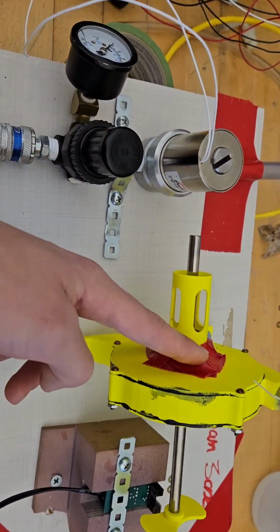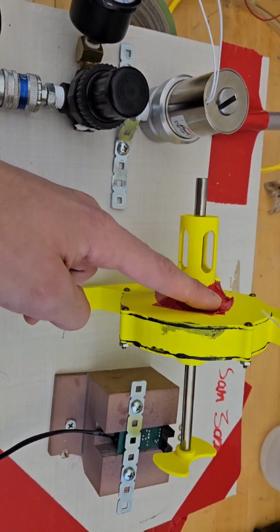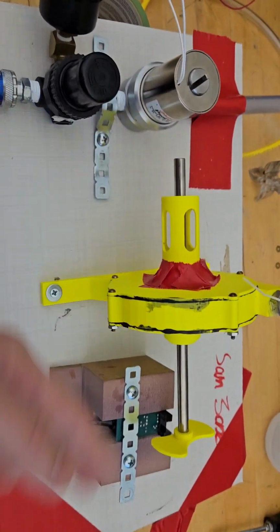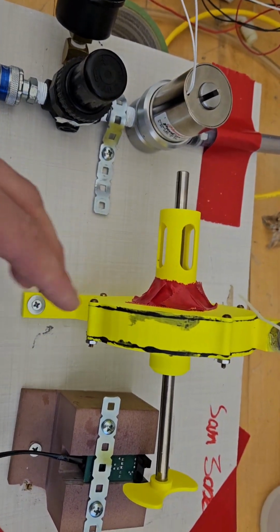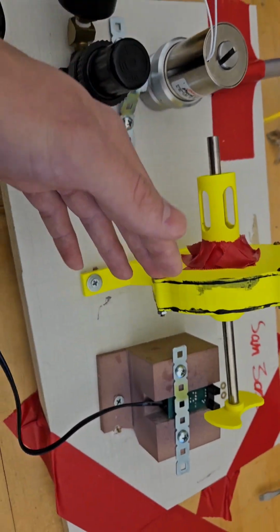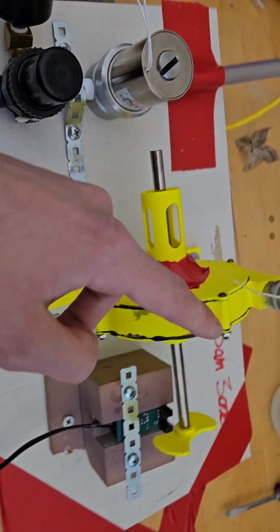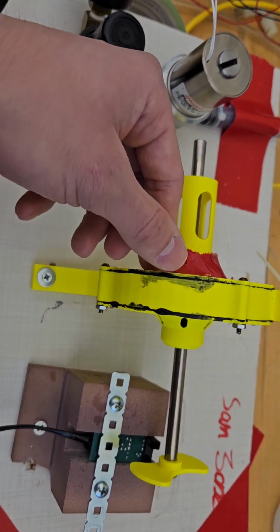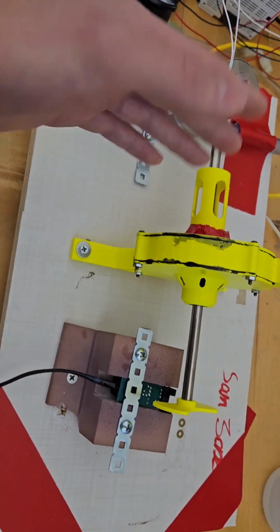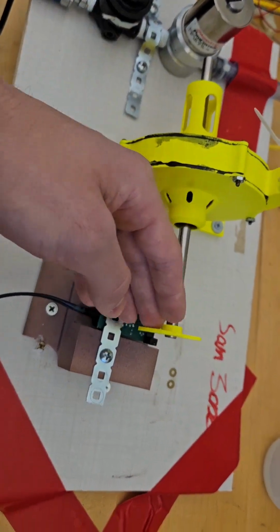We covered up these exhaust ports back here. We were losing a little bit too much air. So instead of reprinting this whole piece, we just decided to tape it up so it sends more air out the front, which in turn makes it spin more efficiently. We did tape this here. This is liquid tape. This is just something we found in our lab. We taped it all the way around on both sides. We were losing a little bit of air through here where they got a little hot during printing and warped. So we just aren't losing any air through there anymore, and it's able to come out through the front.